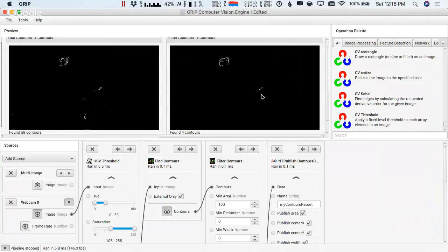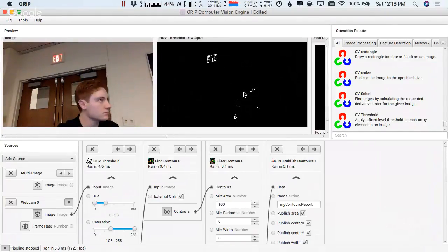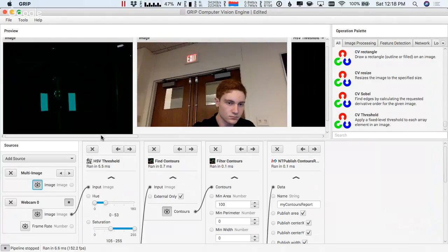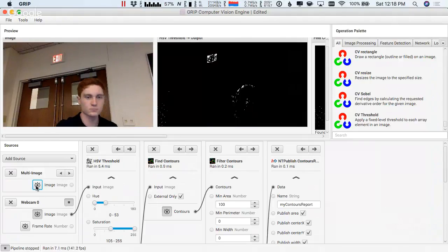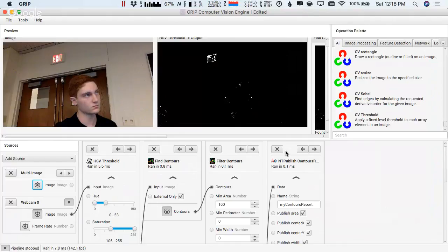There are two avenues to this. I'm going to try that Pixy too. The Pixycam is really nice. I've seen teams that threw it on at a competition because one of the modes you can run is it can give you an analog value for either the X or the Y. They read the analog value and drove the motors at that speed, the differential motor thing.